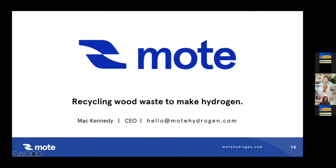Yeah, the question is, where else can hydrogen be used? I think it was more just what kind of infrastructure, if any, can be reused that's already out there. So whether it's pipelines or anything. Yeah, so it's a little bit challenging because people like to say hydrogen is a small molecule and it likes to escape. So in principle, you can use natural gas pipelines for hydrogen, but there are some technical questions about what you have to do to be able to repurpose them.